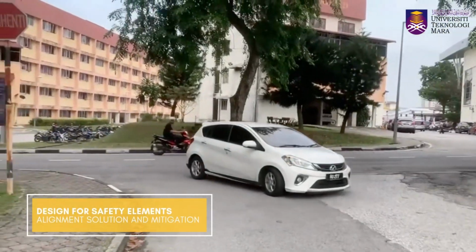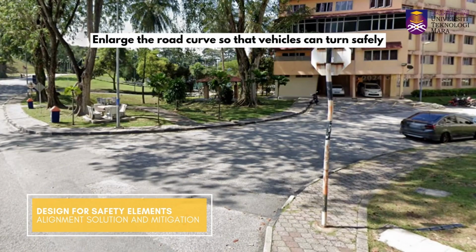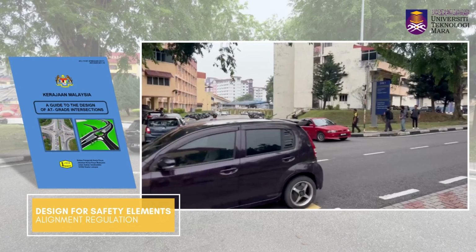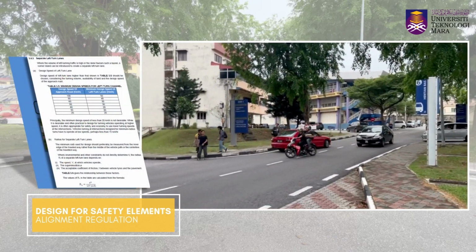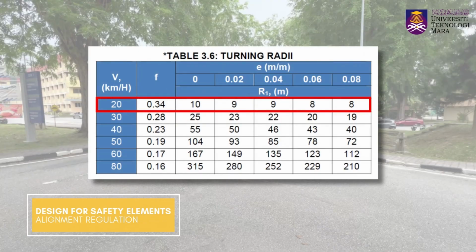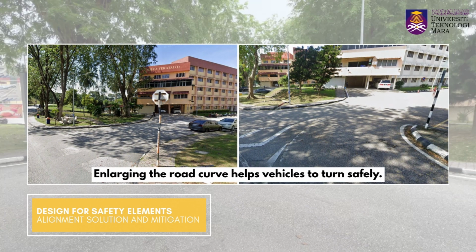In order to overcome this alignment problem, we suggest making the curve for this intersection bigger, so the cars will have enough space to turn left safely. According to ATJ 11/87 section 3.6.3, separated left turn in Table 3.6, there is a guideline for the turning radius. In this case, the recommended radius for a junction with 20 km per hour speed is around 8 to 10 meters depending on the super elevation. Therefore, by following this guideline, the cars can turn safely without any hesitation.